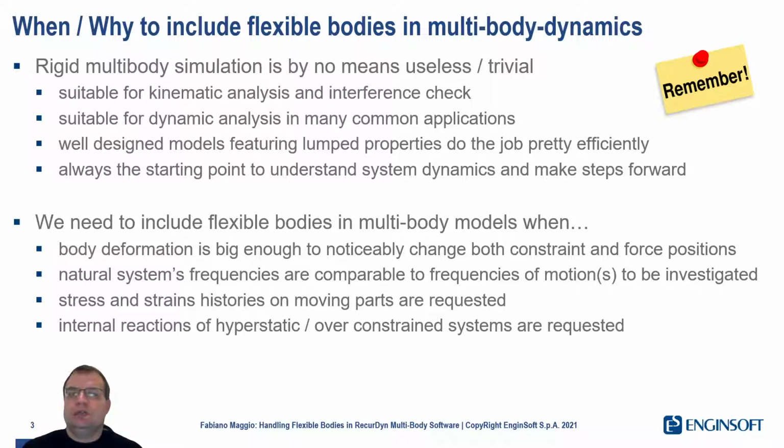When do we need flexible bodies? I think there is not a precise answer to this question, but I tried to find certain situations where this is at least recommended. For sure, if we have deformation of bodies and this deformation is changing the application points for forces and constraints, then in that case we have to have flexible bodies.